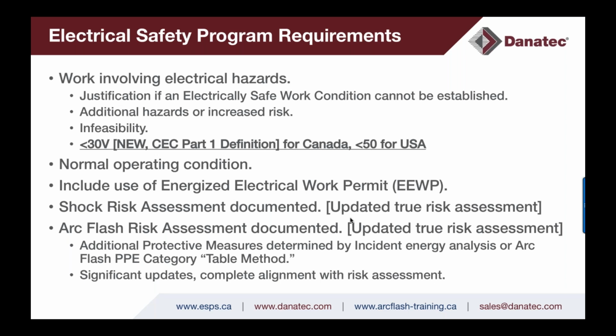Now, the key requirements within 70E and Z462 underneath the risk assessment procedure. So the risk assessment procedure is a separate process from completing a shock risk assessment and an arc flash risk assessment. That's also confused in industry, and I think that some of the training that's available out there, the generic training, doesn't explain this correctly. So the risk assessment procedure is an overarching risk assessment process. There's 2 separate risk assessments that will feed into the overall risk assessment procedure to address severity or potential for injury or damage to health, and that's the shock risk assessment and the arc flash risk assessment. Your electrical safety program should explain this and explain how these 2 risk assessments should be implemented in the field.